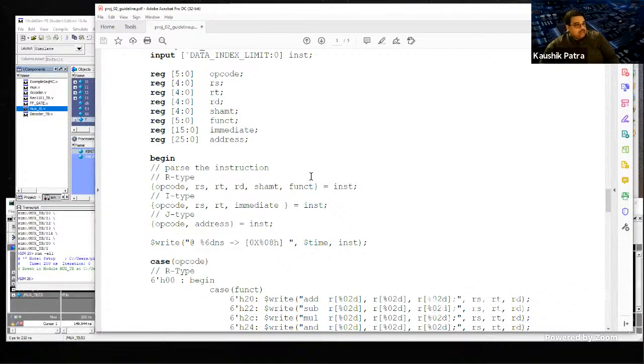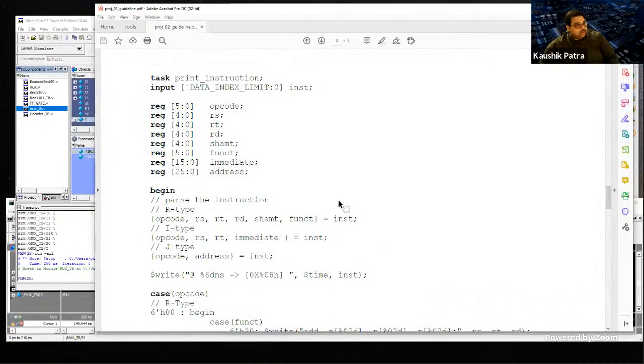What it basically does is your instruction is coming in 32 bits, and it slices and dices this 32 bits into different parts of the instruction. Remember, R type has a format with a group of bits for the instruction code and a group of bits for the function code, then register numbers, and then the shift amount. And for the same instruction, if it is an I type, then we split the field into different parts. So exactly that's what is going on here.